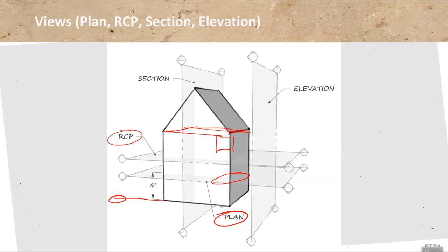Now let's take a look at the vertical sections. If you cut straight through your building, then it's a building section, and it can be done through the entire building. It can be done in any direction. It can be done just through a smaller portion of your building. Maybe you just want to show a wall section, a vertical part of stacked walls, etc. So that is a section, and a section always looks in a particular direction. And I'll show you again in a second how that's indicated on plans, but you can see it already here. The symbol basically tells you which way you're looking.